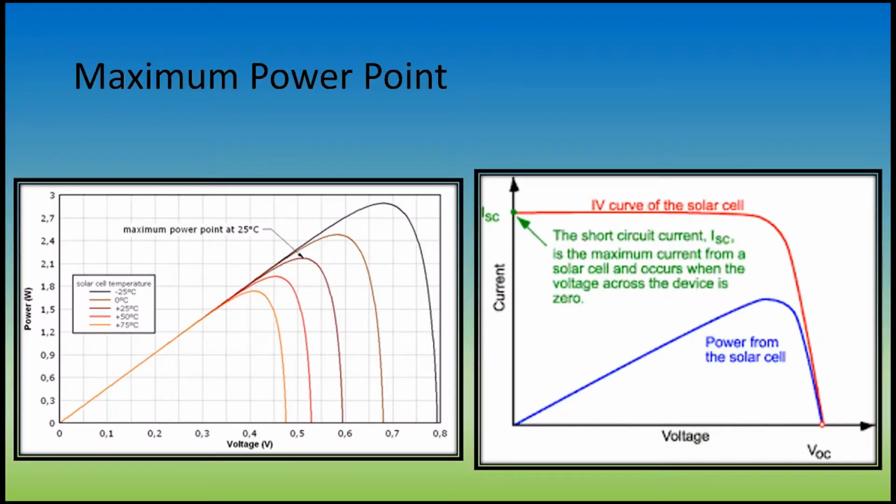The three main factors that play a role in achieving the most power from a solar panel are temperature, amount of sunlight, and load resistance. We will start with temperature. Looking at the graph on the left, you can see the power is greatest with colder temperatures. Why is this? Well, both heat and light vibrate electrons, and because the potential difference between the excited and resting electrons is smaller due to the increased heat, there is a decrease in power.